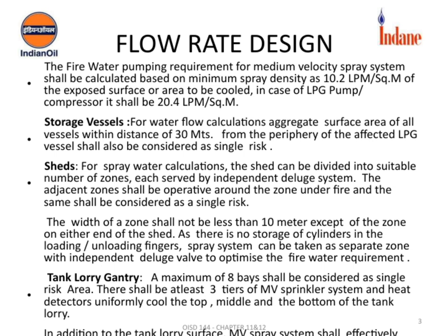Moving on to storage vessels, it's important to consider the aggregate surface area of all vessels within a 30-meter radius from the affected LPG vessel's periphery. This combined area is treated as a single risk, which influences the overall water flow requirements for firefighting.